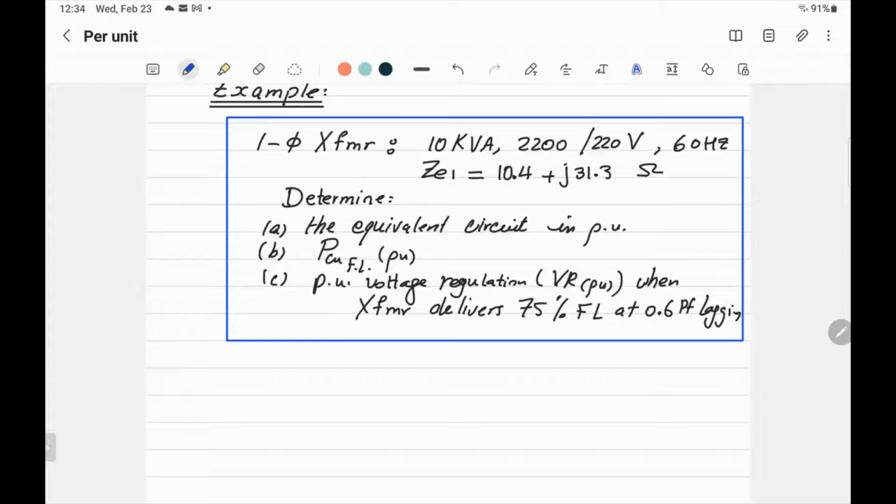Side one or side two, what are you going to choose? Let's say side one. Okay, so in other words, you are going to choose the rated values, right? Exactly. You get the rating values of the transformer, and that's usually what they do in industry. They use the rated value because you want to refer everything to the rated value or nominal value.